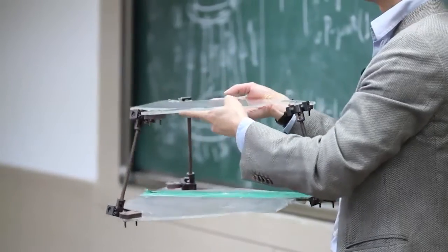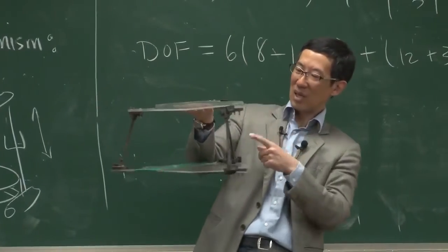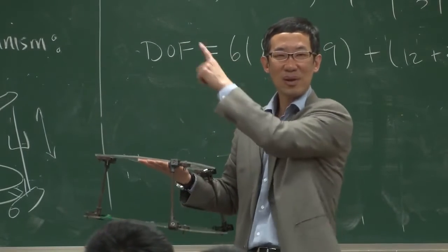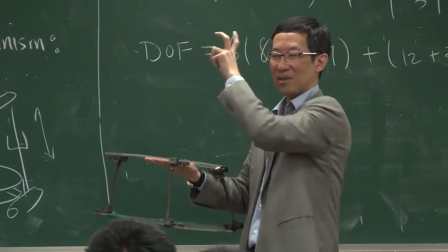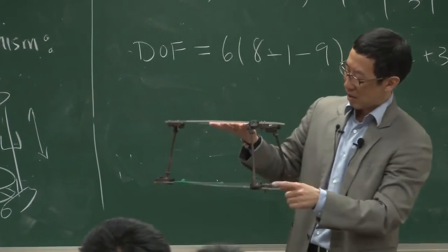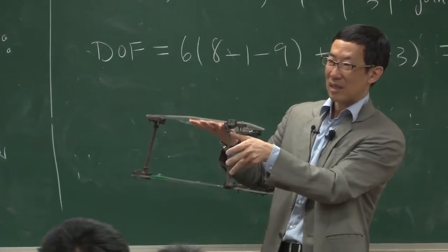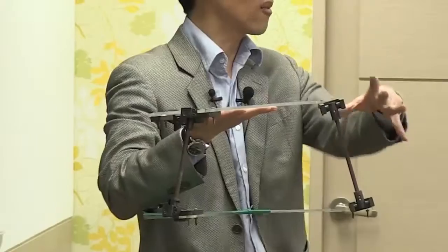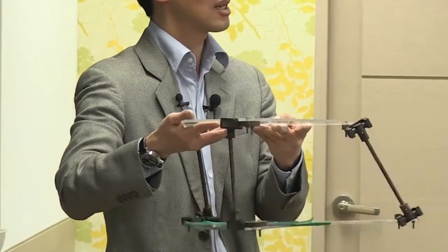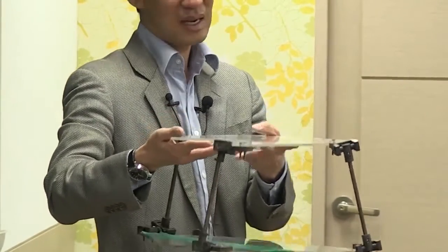Now you might say, hey, isn't this like that planar parallelogram mechanism where all 3 leg lengths are the same and the joints line up? Then it's a special case. Well, if you change the lengths of these legs to be different, it still does this.